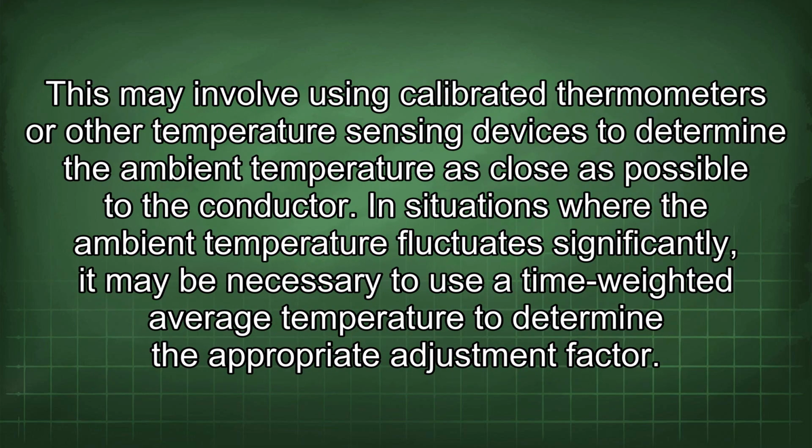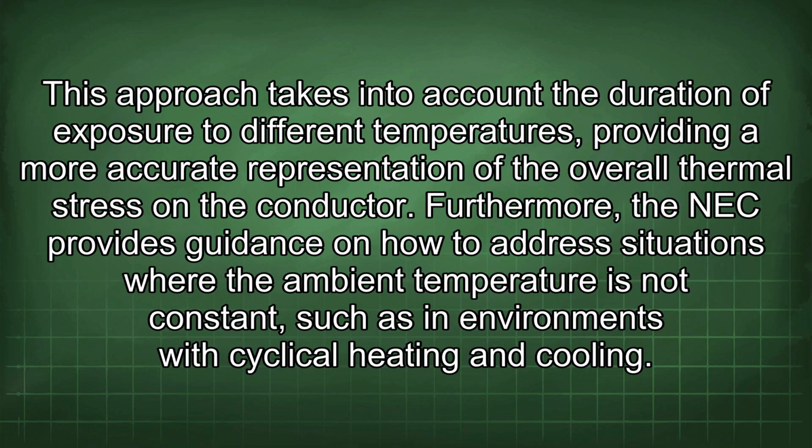This may involve using calibrated thermometers or other temperature sensing devices to determine the ambient temperature as close as possible to the conductor. In situations where the ambient temperature fluctuates significantly, it may be necessary to use a time-weighted average temperature to determine the appropriate adjustment factor. This approach takes into account the duration of exposure to different temperatures, providing a more accurate representation of the overall thermal stress on the conductor.